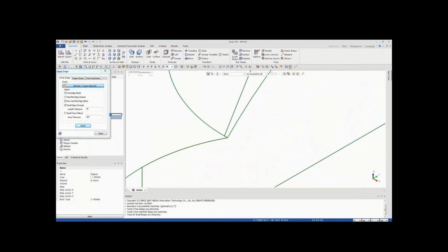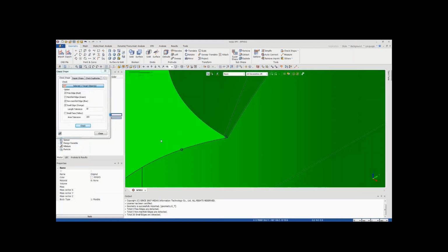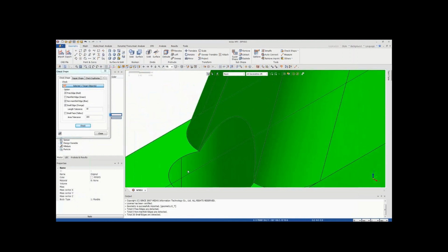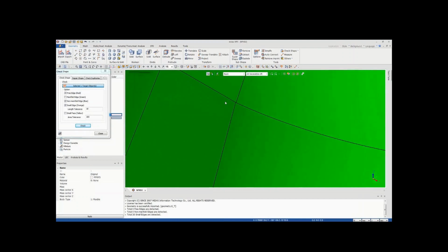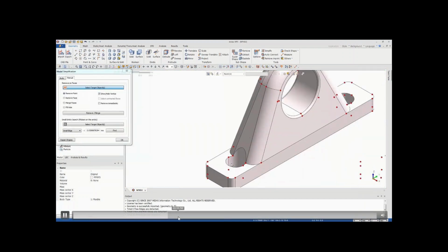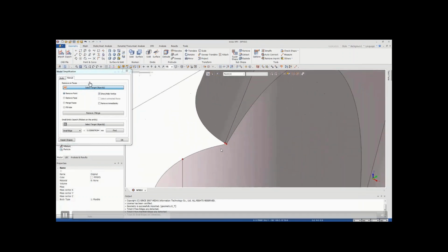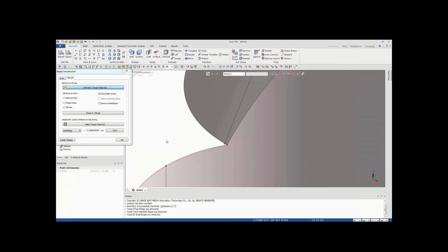As I told you, at the first stage it's very difficult to figure out which value we should use as the limit value for the simplification tool. So now we know the place, and we can simply measure this feature. So now I have got the first value, and I'm going to check other places. I will speed up this video a little bit. So now I'm using manual options, and I'm going to remove this detail by remove point.